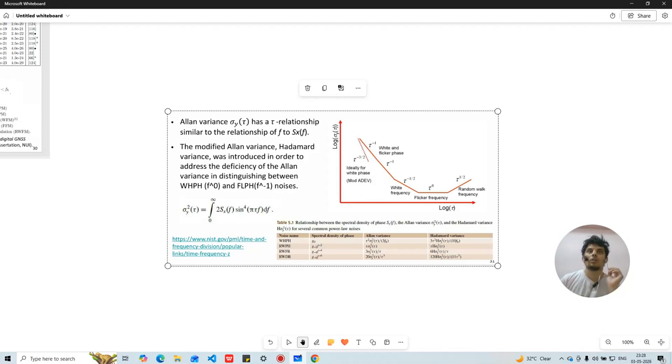Okay, short-term and long-term stability for quartz, rubidium, cesium, and GPSDO. Life expectancy depends on electronics, usually more than 10 years. Rubidium is 5 to 10 years. Cesium depends on electronics, more than 10 years. Frequency accuracy after a 30-minute warm-up: quartz has no guaranteed accuracy and must be set on frequency, rubidium is 5 times 10 to the minus 10, and cesium is 1 times 10 to the minus 12.